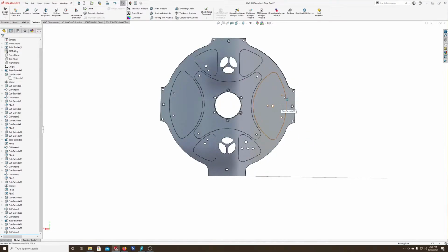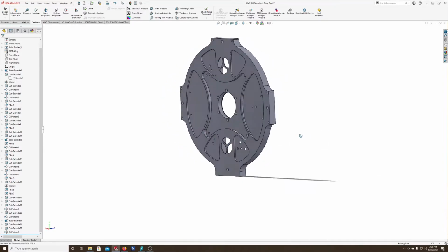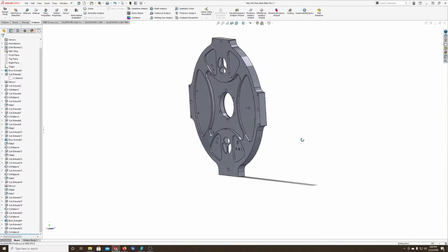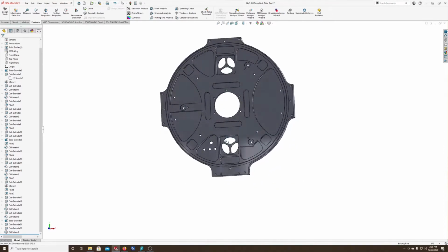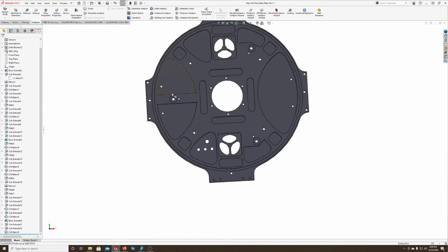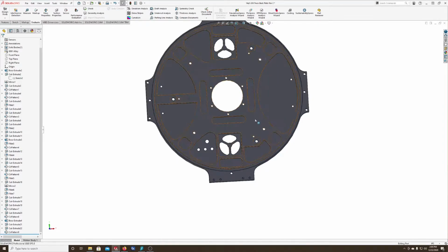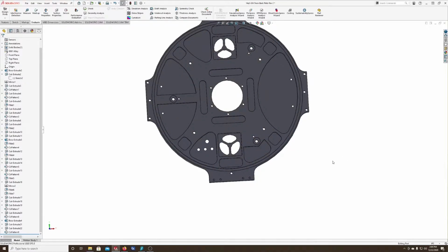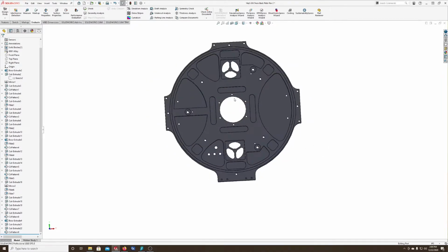These include all the through holes for the screws, for the handles, and to attach other plates to it, where we attach power connectors and the potentiometer to control the fan speed, holes for the optical path, holes for the fans to get air, and then lightweighting pockets. There are also some features on the back where the collimation adjustment screws will go, and the springs that go in there, as well as some lightweight features back here.